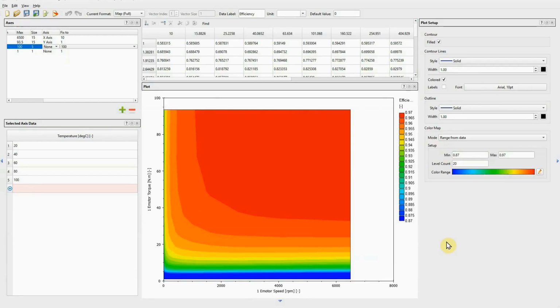That has not cost us anything in terms of the design. We haven't had to do anything to any of the lubricant conditions. We have just replaced one gear design with another and replaced a couple of the bearings with more efficient bearings. We have the same durability as we had before, and a significantly improved efficiency, which should make a noticeable improvement to the range for our electric vehicle.